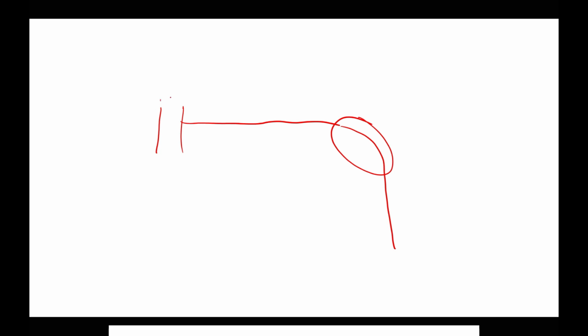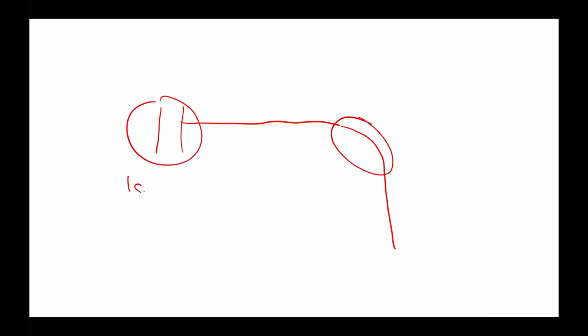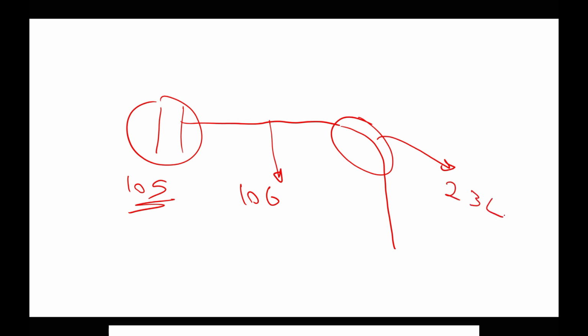We know that we have a lot of carbon steel material. Say we have a flange welded to a spool, and at the end of the spool we have a 90-degree elbow. Let's say the flange material is A105, and if it's an ASME material, then it's SA105, which won't make any difference for us. Let's say the pipe is SA106 grade B, and the elbow material is SA234 grade WPB.